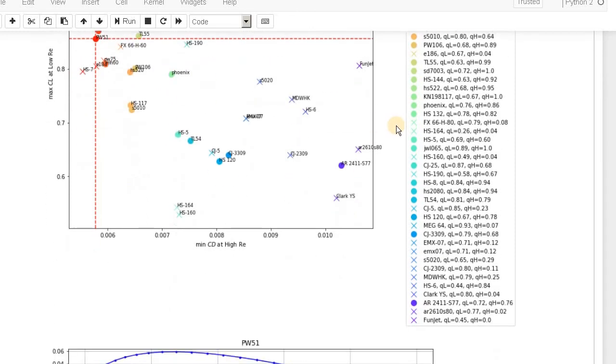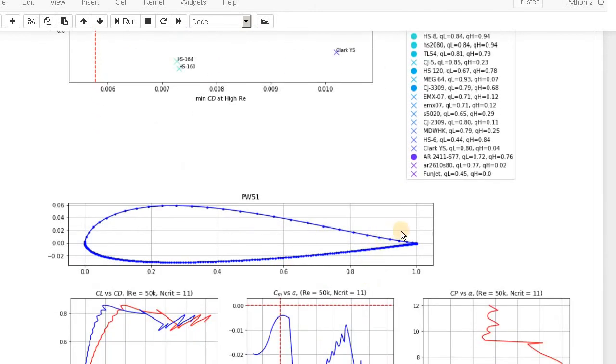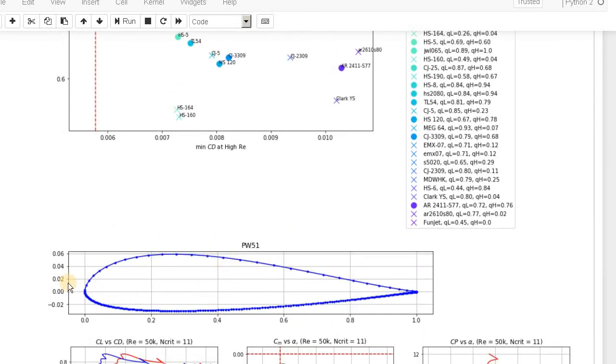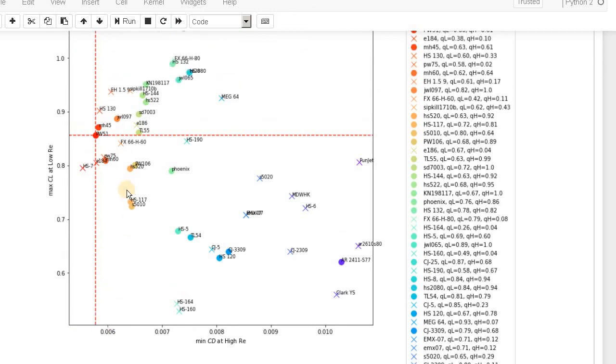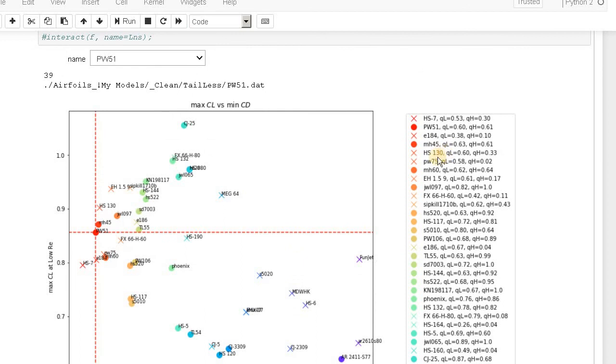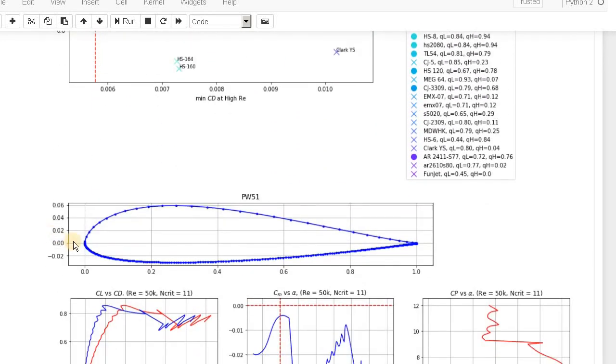The simple solution would be to deflect your flaps. In that case, you might get a stable airfoil, but you're going to have an increase in the drag and lose efficiency. So your beautiful airfoil is going to move to the right side, and you're going to have high drag for this particular airfoil. The second solution is we have to move from the one-dimensional creature living on the chord line to the two-dimensional space, and maybe find a place for our center of gravity somewhere below or maybe above the airfoil.